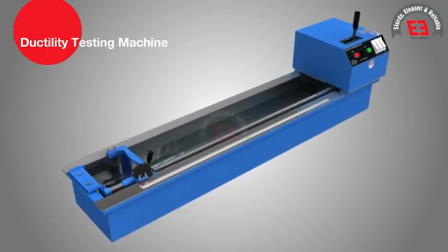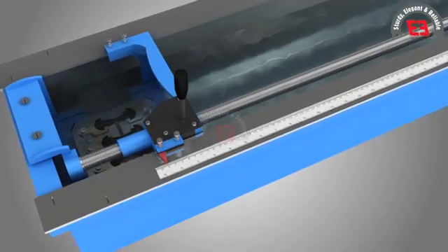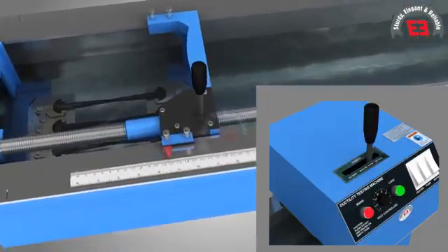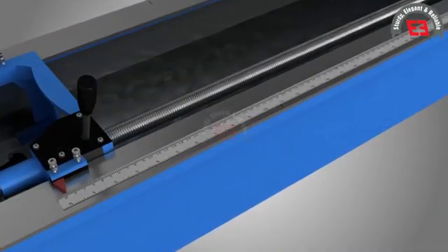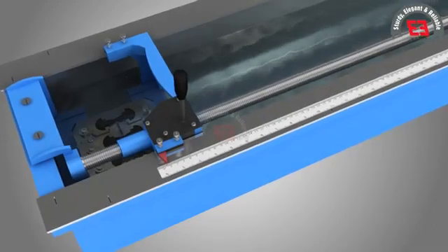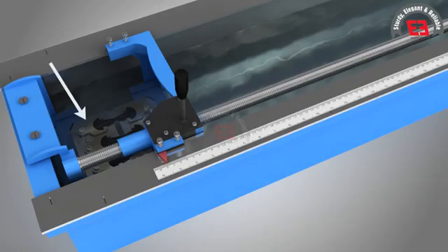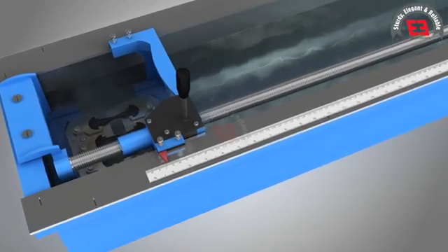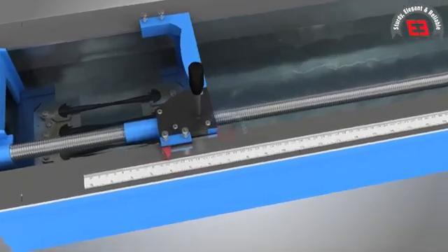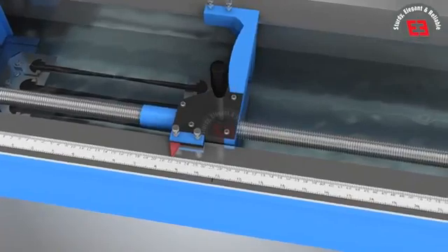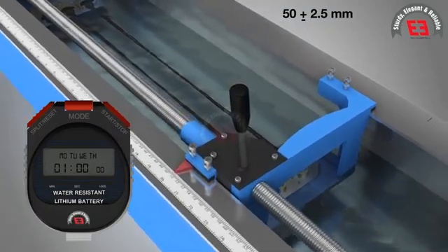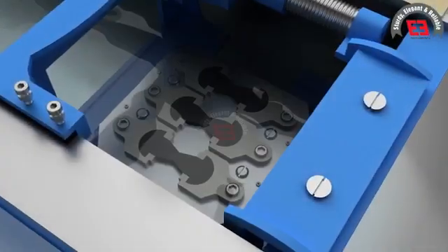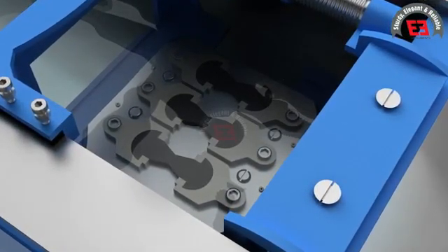Ductility testing machine. This apparatus is a constant water bath type with a pulling device at a pre-calibrated constant speed of 50 mm per minute and 10 mm per minute. The central rod of the machine is threaded and through a gear system provides movement to the ductility molds, the clip of which is fixed at one end and the second clip is stretching the thread of bitumen binder away from the first clip. The 2 clips are thus pulled apart horizontally at a uniform speed of 50 mm per minute, plus or minus 2.5 mm per minute. The machine has a provision to fix 3 ductility molds at a time.